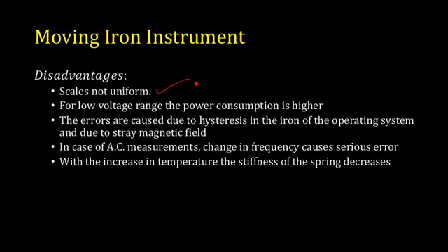Now the scale is not uniform. This is one of the disadvantages. The scale has non-uniformity at the starting and towards the end. Now when you are using it as a voltmeter, your power consumption is higher for the low voltage range because you will have a fixed resistance.